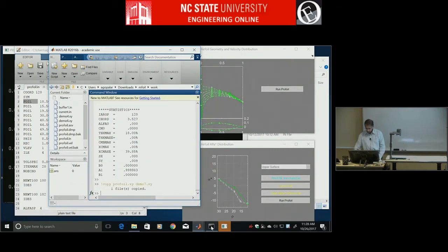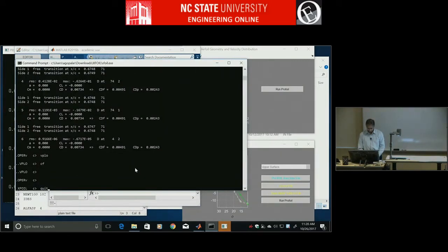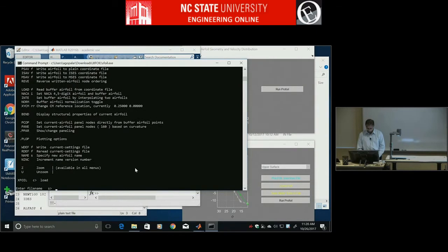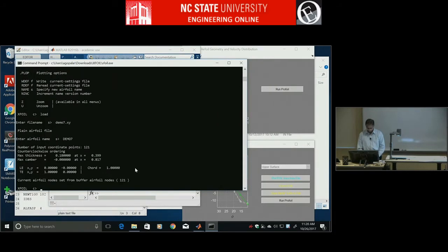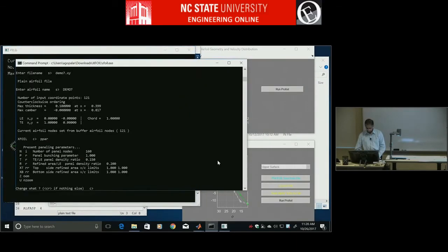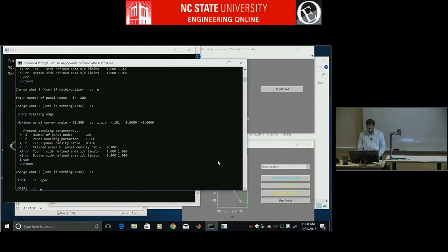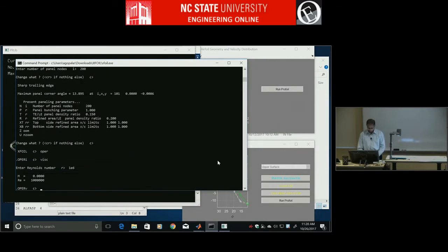We'll go run Xfoil. Load demo 7.xy. Reynolds number 1,000,000, alpha 0.